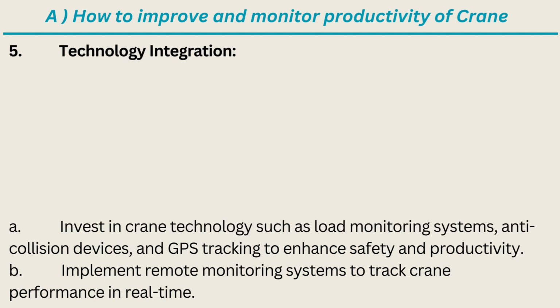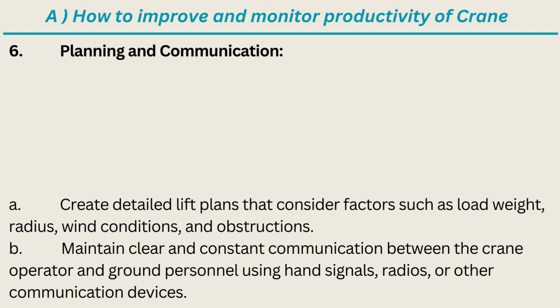5. Technology integration. Invest in crane technology such as load monitoring systems, anti-collision devices, and GPS tracking to enhance safety and productivity. Implement remote monitoring systems to track crane performance in real time. 6. Planning and communication. Create detailed lift plans that consider factors such as load weight, radius, wind conditions, and obstructions. Maintain clear and constant communication between the crane operator and ground personnel using hand signals, radios, or other communication